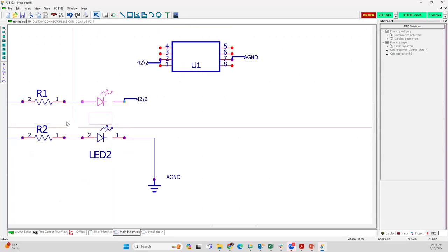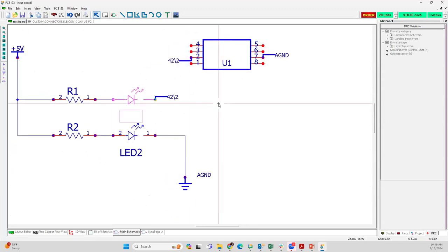But you go to DigiKey and you can look at the specifications on the data sheet. Use that to check your footprint, make sure that it's going to fit, make sure that it's a common part that they do stock and that is available.